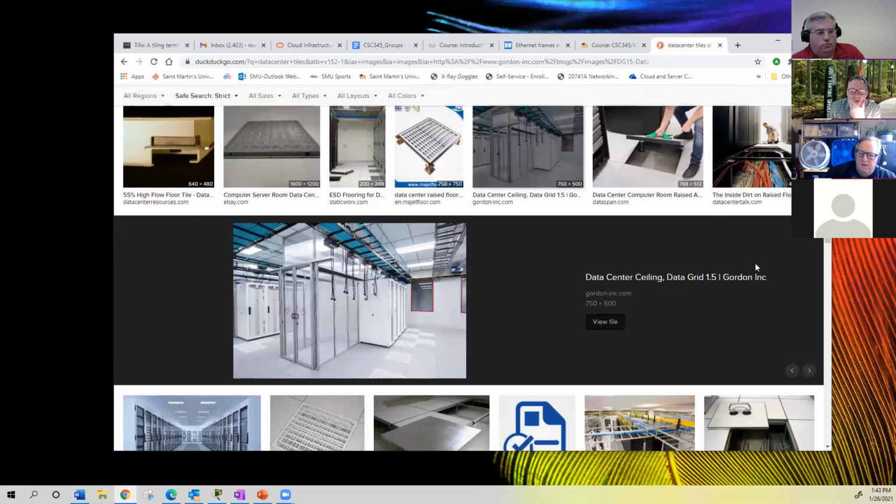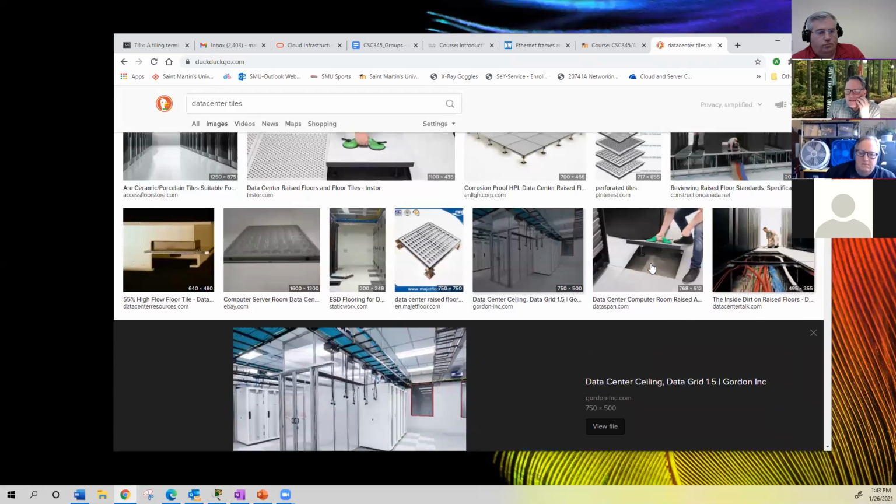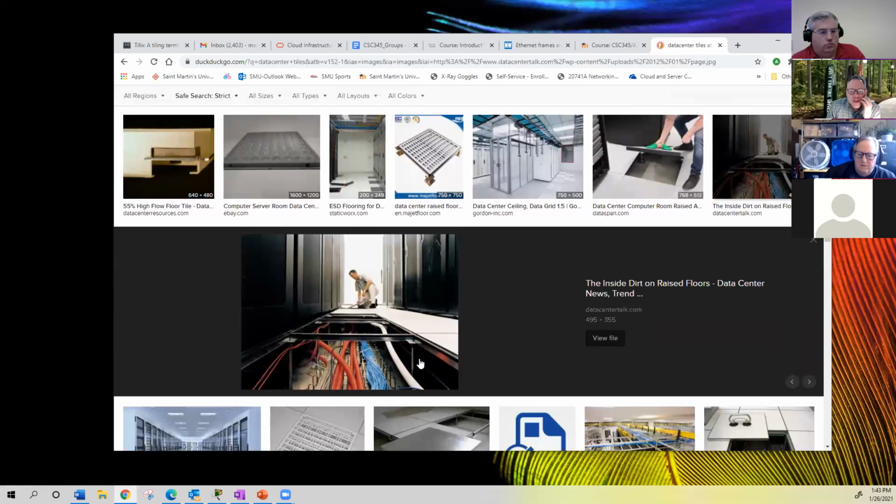These are just a little more idea of what goes in. You put all of your cabling and power, here's your fiber optic in the orange, and your copper and other runs. They have underfloor trays that hold this, and you try to keep it separated. You put this through your hot aisle so that it's not running in your cold aisle and blocking airflow getting into your cold aisle. If that makes sense.